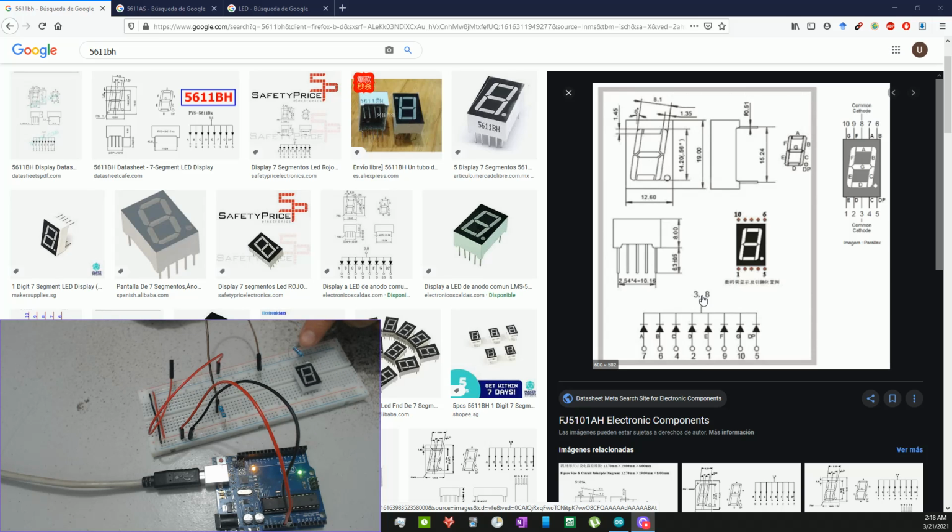The 330 ohms alone, it's not enough to restrict the current connected in the common connection for all the LEDs. It might work. Actually, you may be able to identify some circuits with a 330 ohms connected in the common element. And it is going to work. It's fine.